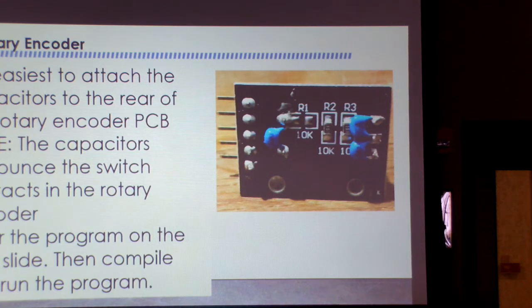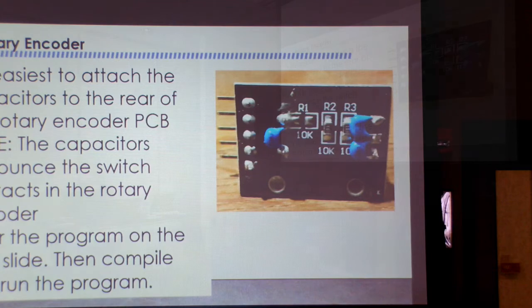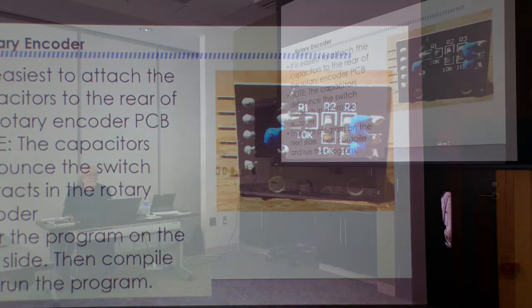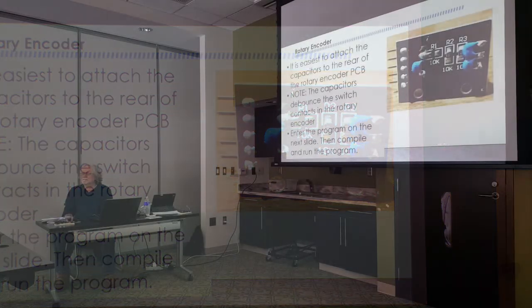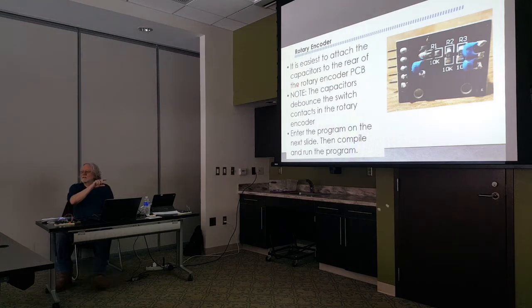Because what I showed you, the software I gave you, had debounce in it. No, it's polling the pins, slowly, so the bounce takes place during the time the processor's reading all these things. The reason I put them on there is the other method of calling a rotary encoder, which is in the example projects for that library, is you do it with an interrupt.